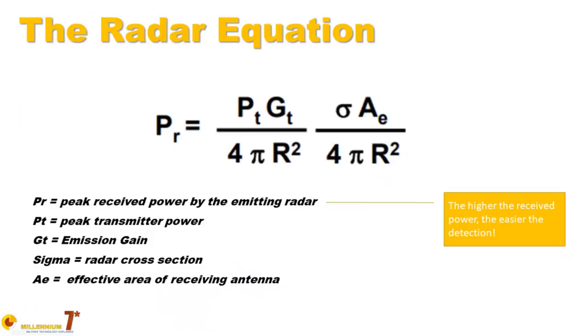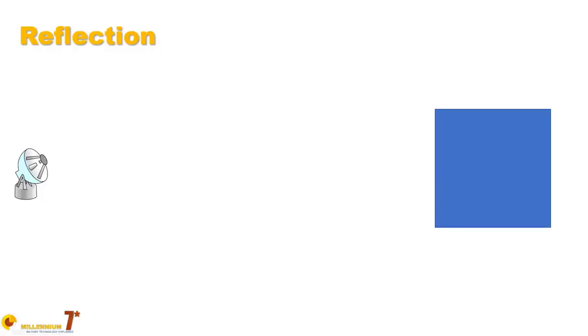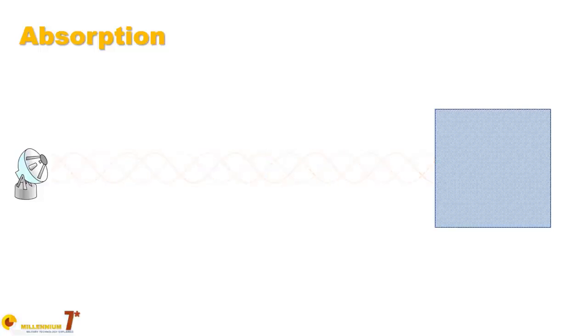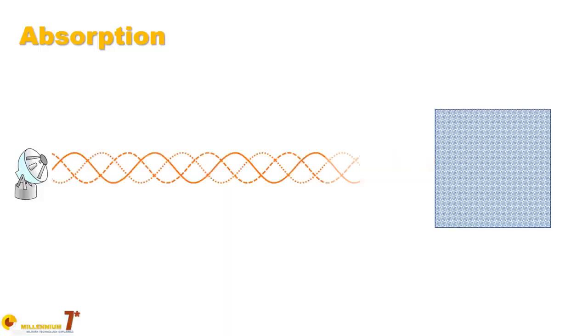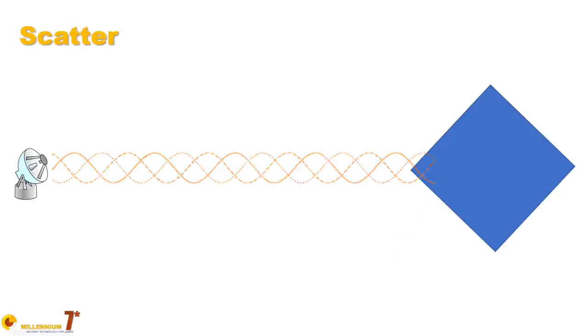To reduce the detection probability of a radar, what you want to minimize is the power of the reflected signal toward the radar itself. There are two main methodologies to do this. One is radar absorbing materials. They reduce the energy bouncing off the surface that they are covering by simply absorbing part of it. Two is the reduction of the specular reflections toward the emitter, which is normally obtained with the typical shapes that you see on stealth aircraft. When we have applied these two principles, we have done already a quite good job, but still there's quite a long way to go.